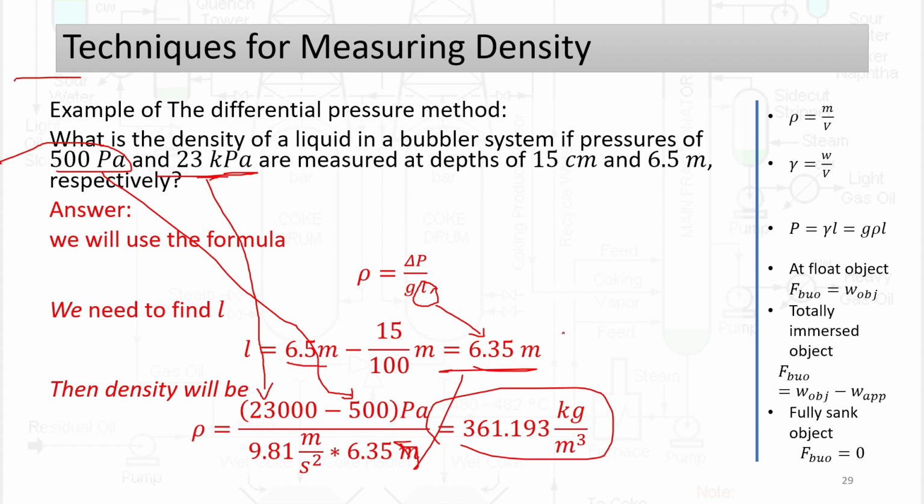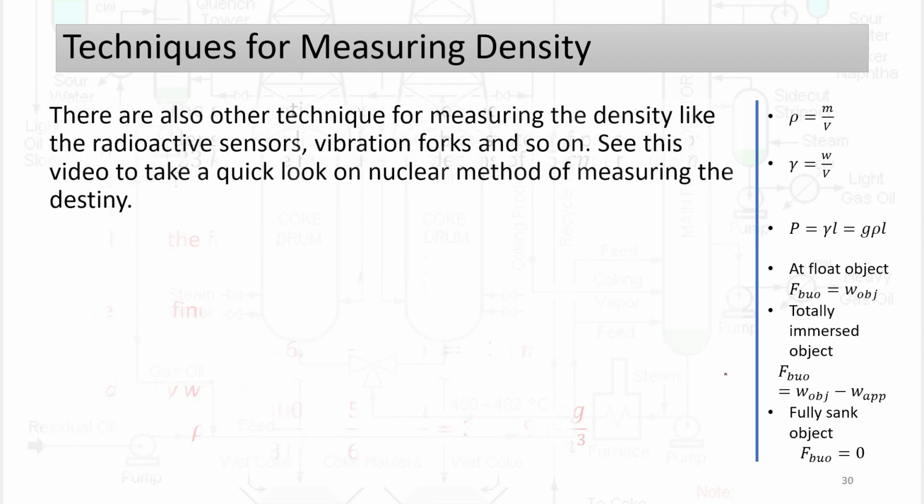So this is the simplest method. It is a simple method and it is helpful. Most of the time it is used for reservoirs and tanks, because here you just put a simple tube, not costly. So if you have some corrosive material or some harsh material, just put a tube on it. Even if the tube is corroded or exposed to corrosion, you can change it simply and it's not that costly, in order to save your devices or your sensors.